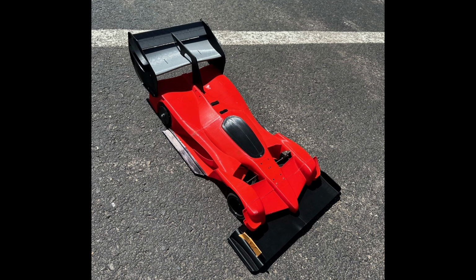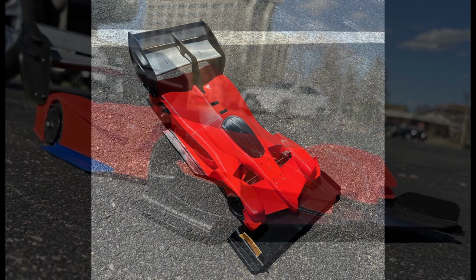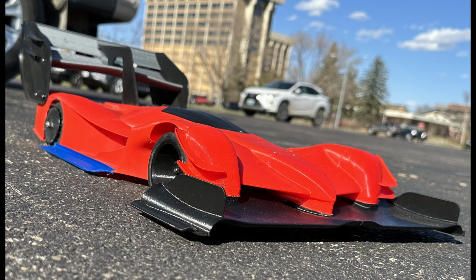Tentatively, I want the car to be able to pull 3+ lateral Gs at a very tame 60 miles per hour or 100 kmph. And this is quite the challenge as aero forces increase as a square with velocity. So a car going 60 miles per hour only generates 1/4 of the downforce it would at 120 miles per hour. The wings and the aero devices on this car have to be absolutely massive to be able to generate downforce at these speeds. And to make matters more challenging, any weight I add from the wings or aero devices adds weight to the car, which means I need to add more downforce to compensate.